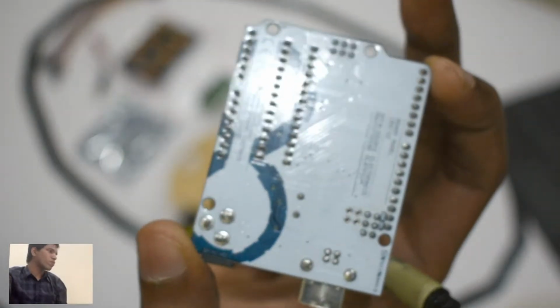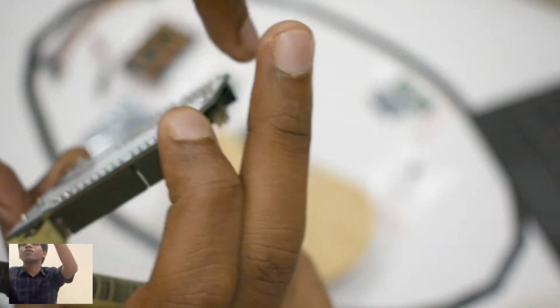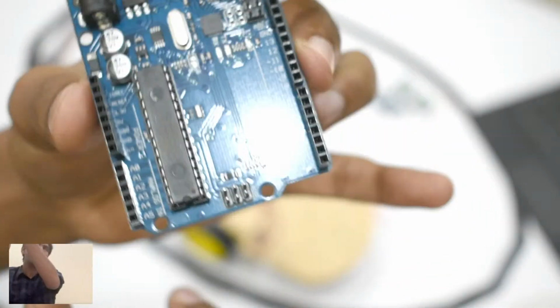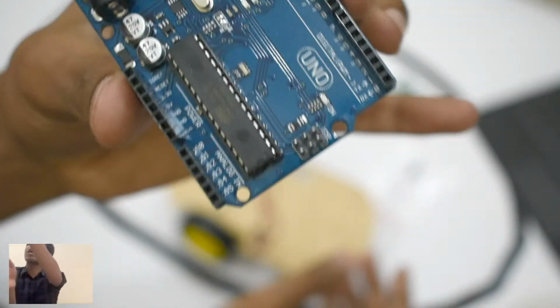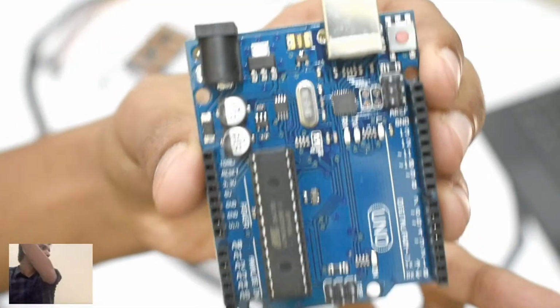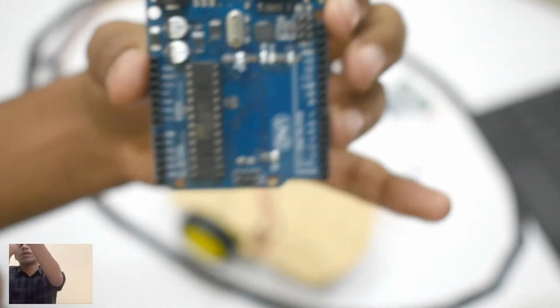First of all, while handling these circuit boards like this, you can see all of their pins are exposed at the back. Do not ever put this on top of a metal surface. You're going to short all of these pins. Okay, these are very delicate pieces of circuit. You have to hold them by the side or put double-sided tape at the bottom of it so that you never short it by mistake. Okay, hold them by the side always and just use them carefully.